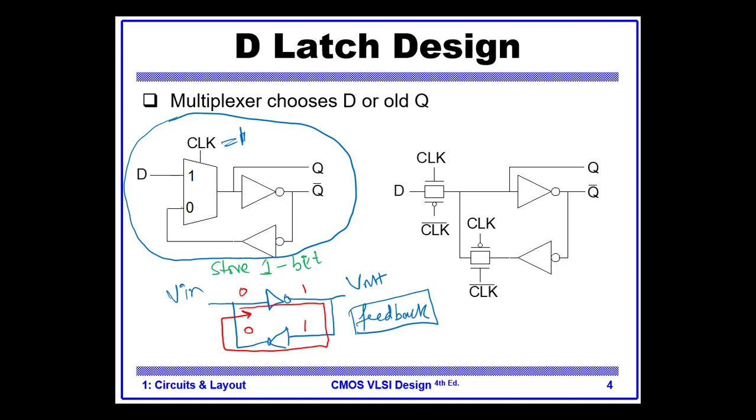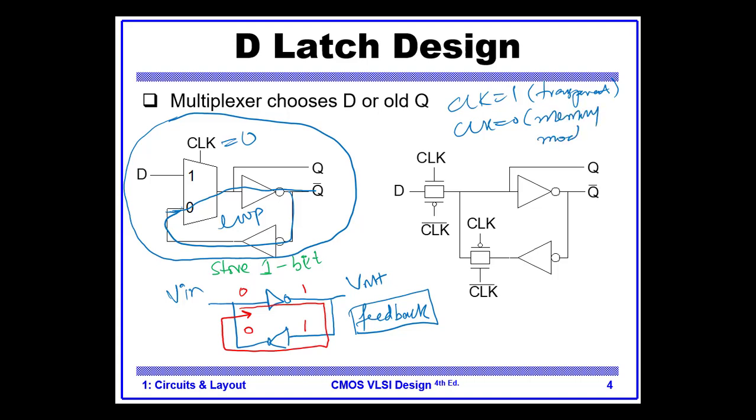And when it is 0, then this other path is selected, and it goes like this and comes back like this. So we have the loop. So when clock is 1, it is transparent. When clock is 0, it is in memory mode.